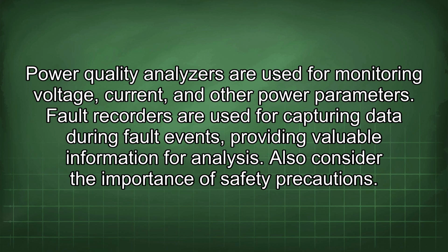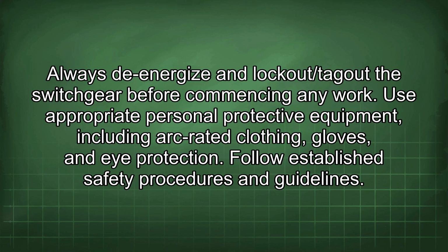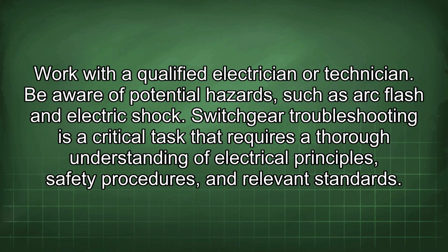Also consider the importance of safety precautions. Always de-energize and lock out/tag out the switchgear before commencing any work. Use appropriate personal protective equipment, including arc-rated clothing, gloves, and eye protection. Follow established safety procedures and guidelines. Work with a qualified electrician or technician. Be aware of potential hazards such as arc flash and electric shock.